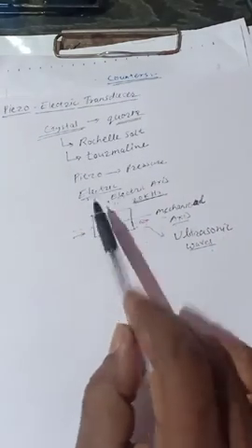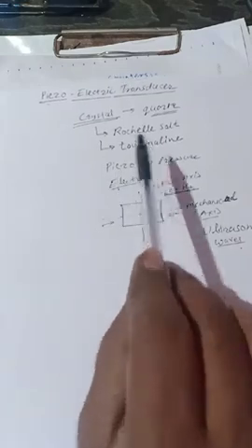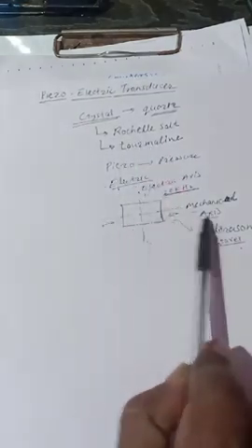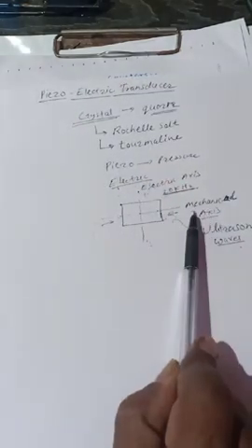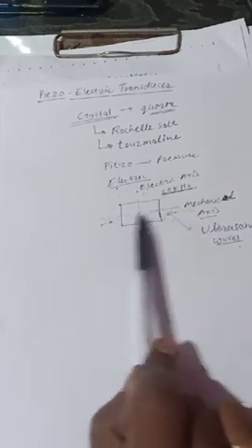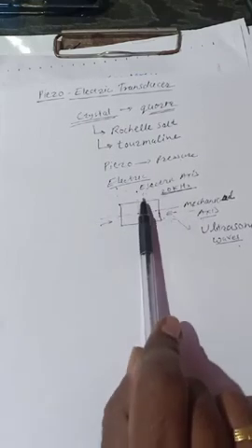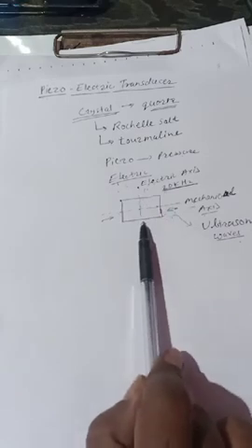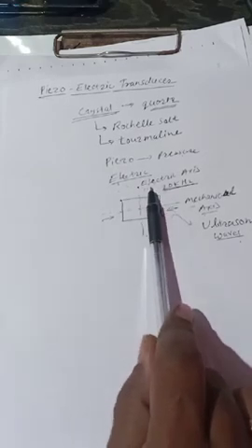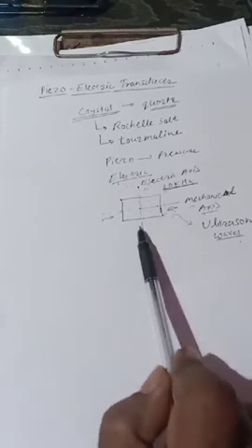So this is the piezoelectric property of this material. If we apply a mechanical pressure on the mechanical axis, it generates an electrical signal, a changing voltage, on the electrical axis.